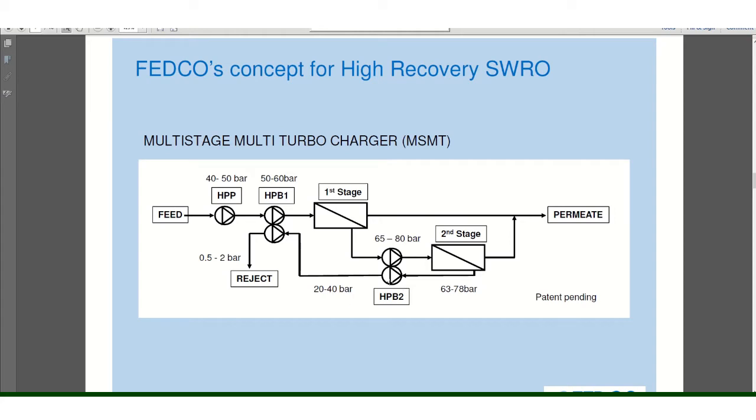And here's the idea: because the turbocharger here is very highly efficient, the amount we need to boost is less than what we can generate from this turbocharger. For that, we send the extra amount to the first turbocharger, or the feed turbocharger, and we recover this amount, and after that we pump out the reject.